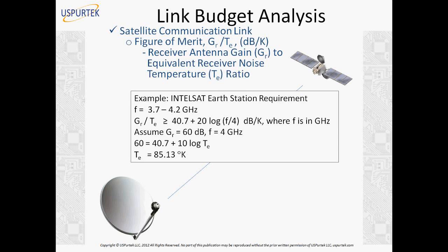Now for deep space communications, they may have to be supercooled receiver antennas, the kind that NASA or any other space organization will use. In any country, they have to use supercooled antennas. The objective is to bring down the temperature of the antenna so that there's less noise. Right? Because signal level is what it is. What we are receiving, that is the signal level. You could have a higher transmitter gain and all that stuff, but there are restrictions or limitations. So the other approach for a deep space communication link is that we reduce the noise level of the receiving antenna itself by supercooling the antenna.